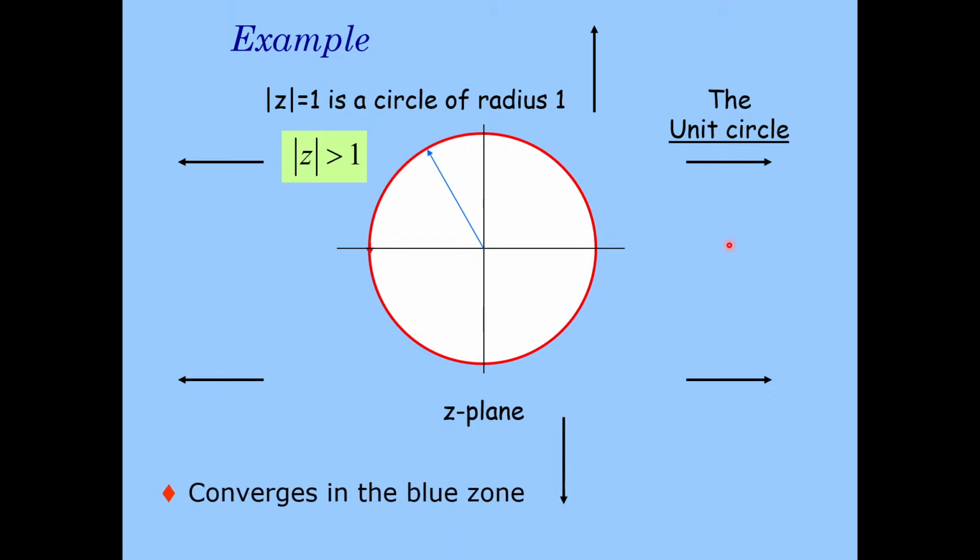So the region of convergence, depending on what the magnitude of z is going to be, more than 1 or less than 1 accordingly, or any certain value, will determine which parts you're going to be shading in your z domain. So I'm just going to give you guys an idea of what's going to happen if we didn't have a value of 1 here. So let's say if we had magnitude of z here being less than 0.5, and let's say I'm just going to draw my z domain plot here.